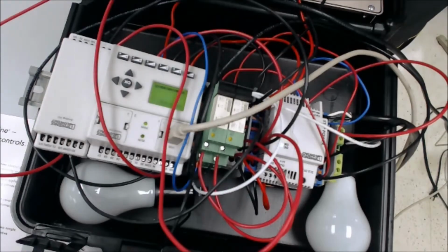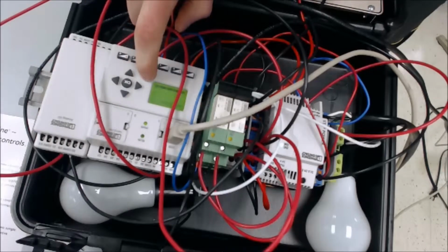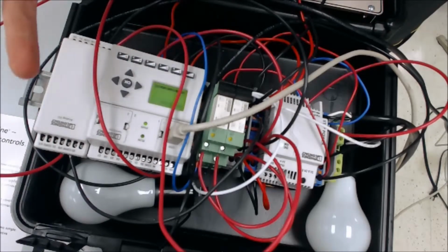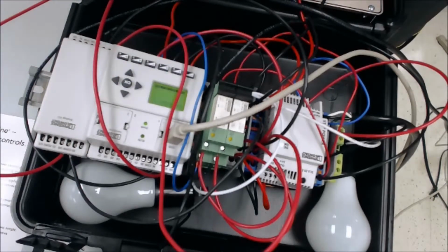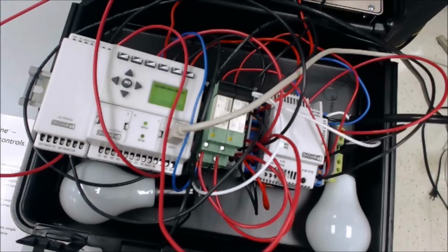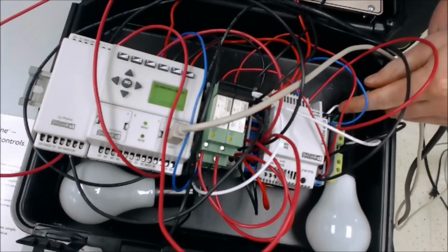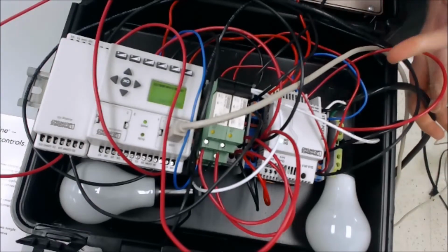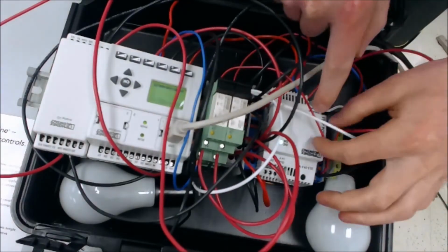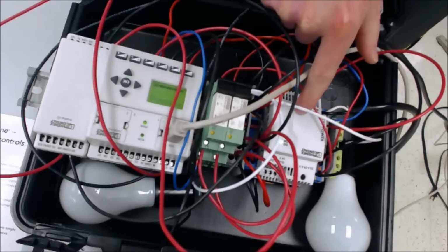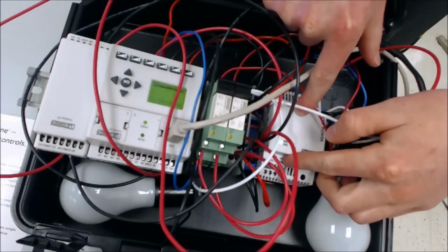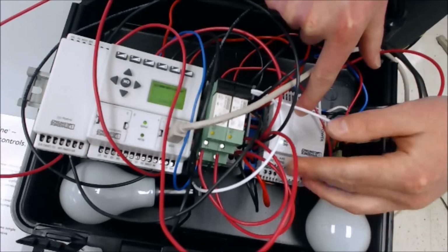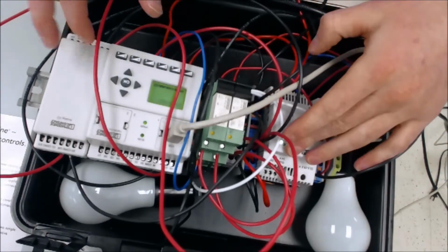So this is the actual PLC rack that we used for the lab. This is the PLC, and its job is to just perform logic on all of the inputs and create corresponding output signals. Now, it's all powered from the wall right here. This wall power initially goes into a switch, and this switch then goes into this step-down power unit that converts the AC signal to a DC signal, and this 24-volt DC signal is what actually powers most of these modules.